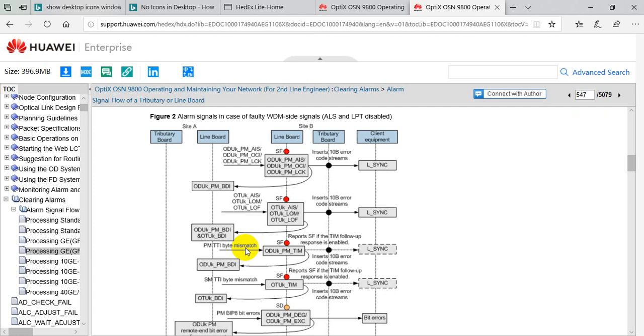Sometimes in the same 48 fiber there can be multiple OTN networks of your own operator, or it may be of some other operator. While the frames are ITU-T standard, so the frame is fine and there won't be any alarm, to avoid that kind of scenario, you can put your identification per operator and you can enable this alarm.